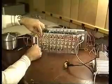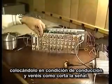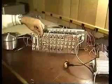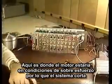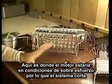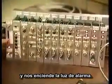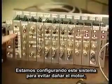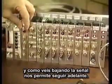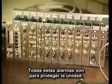Alright, let me take the inhibit off. We'll put it back into trip mode and you'll actually see it shut down. And there's where the engine would have gone into an overspeed condition and we shut the electronics off, therefore allowing the safe operation of the car. We have an alarm light on. We're sitting at a high tach. We had an overspeed trip. If I bring the system back down, I'll allow it to cut back in. We have all of these alarms set up to protect the unit.